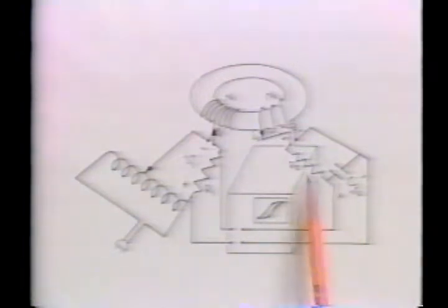Thus, by connecting the terminals of the sensing coil through the integrator to the vertical trace of the oscilloscope, we make the vertical axis proportional to B. So, we should see a display of B versus H on the oscilloscope.